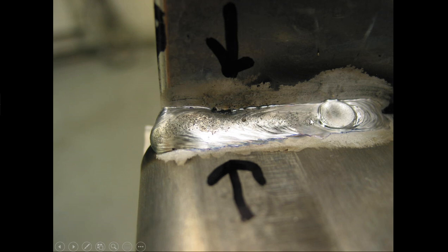And all this should be setting off a few warning bells about the cleanliness, or maybe how dirty that nozzle is. And remember, even though it's going to a reamer, somebody might say, it's going to the reamer, it's okay. All the spatter I'm talking about accumulates way up inside, right around the diffuser and the diffuser cover if you're using Fronius. So it's got to be cleaned out a little bit because we could be creating some issues.